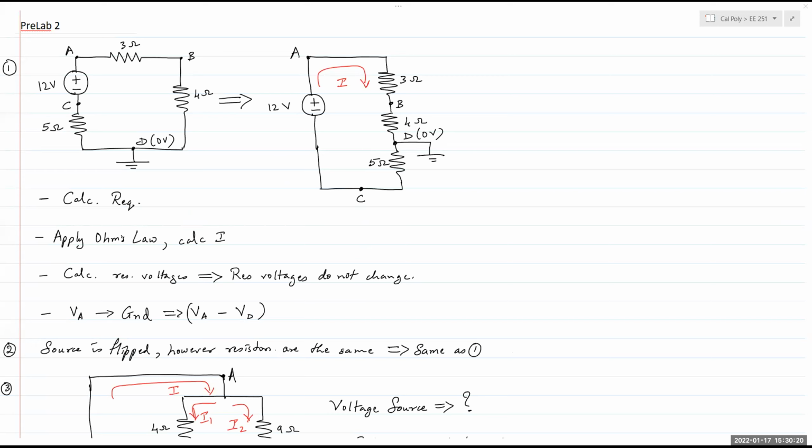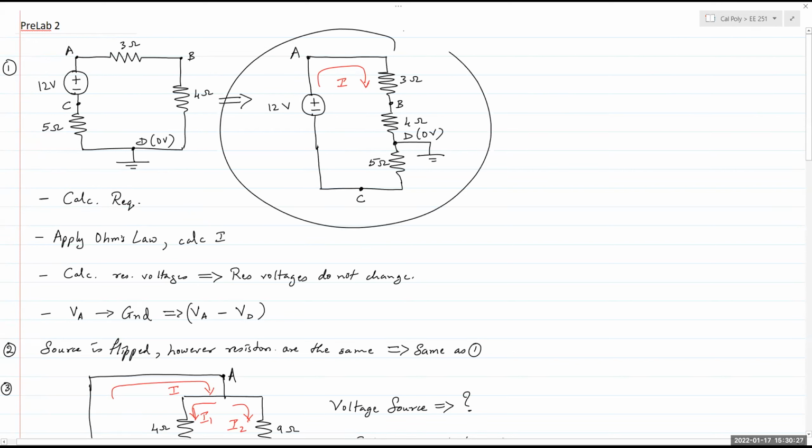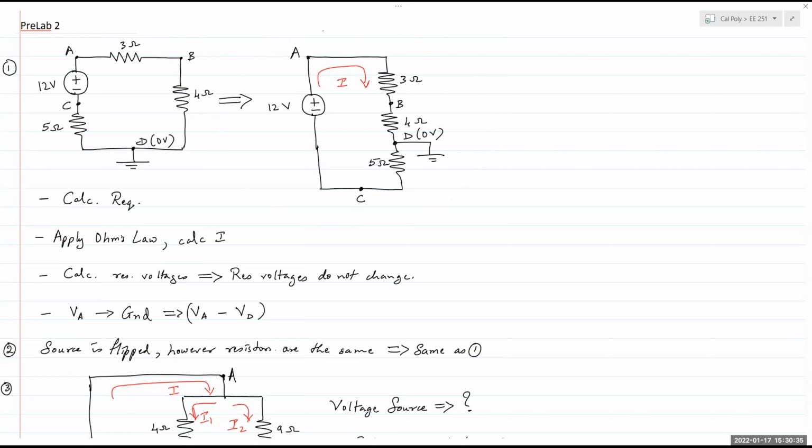In the notes, I have the original circuit here on the left, and then I've redrawn that circuit here on the right. Now, redrawing the schematic does not mean that I'm actually changing the circuit. I'm just redrawing it in a way that would make sense to me, and hopefully to you. So as we can see, all 3 resistors are connected by 1 node each, and if there is a connection between 2 components at a node, we say that they are in series. And so that's the case here.